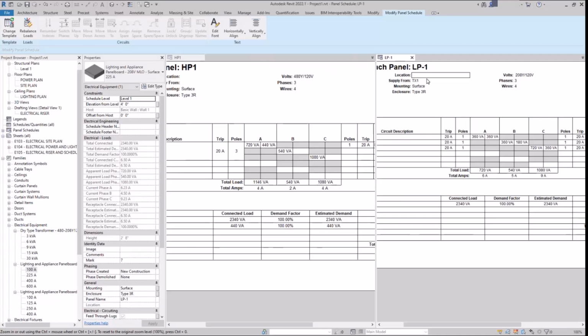If you're actually doing a full-fledged project, people on YouTube use what are called spaces. There are rooms in Revit and there are spaces in Revit. Rooms are for architects, spaces are for MEP. The MEP world can pull information out of spaces. There's literally no difference between the two other than one is for one and one is for the other.